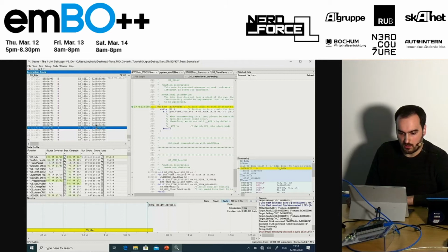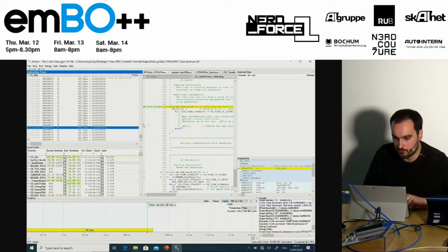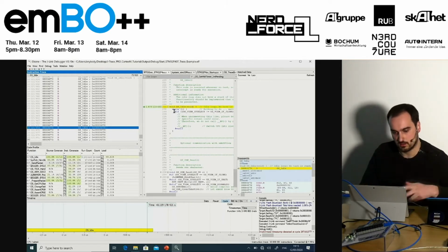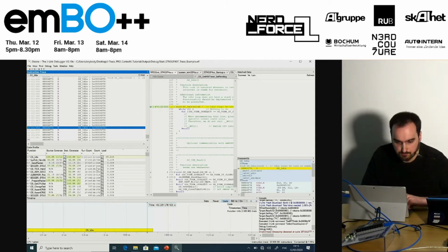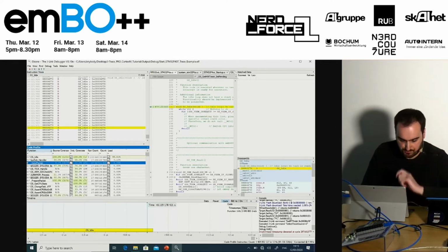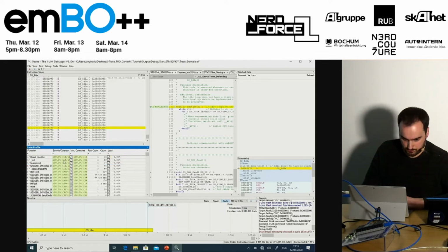Now to pick up this code coverage talk we heard earlier from Marius. So this is also something that you can do with this tool. We take this information that we gather live with all these updates, and we know what has executed when and how long. We get timestamps, so we're cycle accurate here. And you can also find here the code profile and code coverage window, which gives you information about your source coverage. So if I sort by source coverage, you see, okay, reset handler has been fully executed.